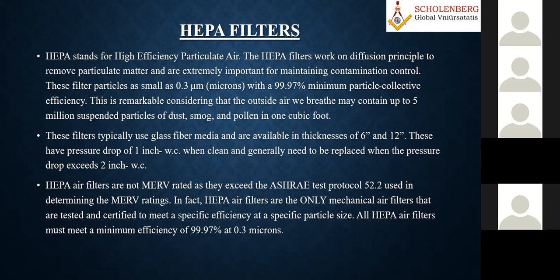What I'm telling you is that we have different kinds of test protocols. Some of the tests I'm going to explain in the subsequent slides. So HEPA filters do not come under the MERV rating. In fact, HEPA air filters are the only mechanical air filters that are tested and certified to meet a specific efficiency at a specific particle size. All HEPA air filters must meet a minimum efficiency of 99.97% at 0.3 microns.